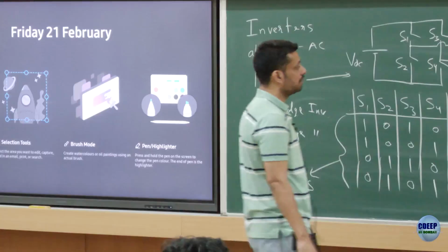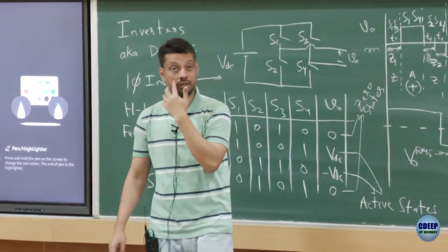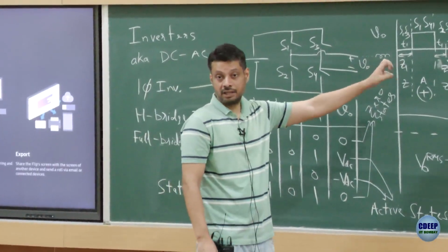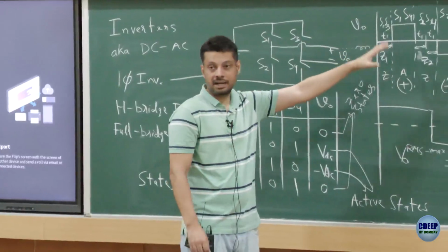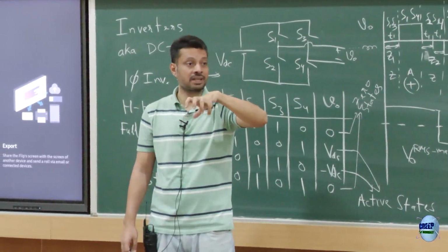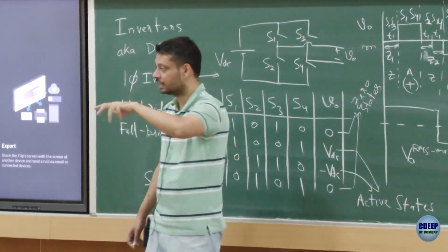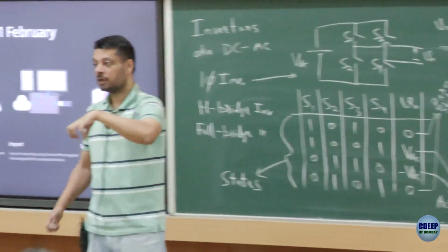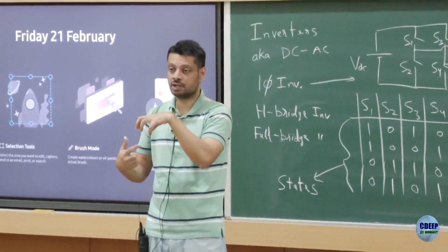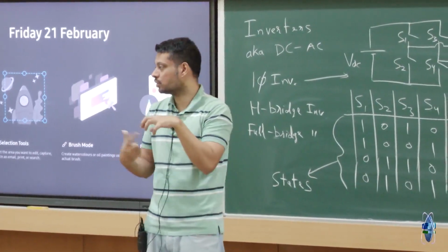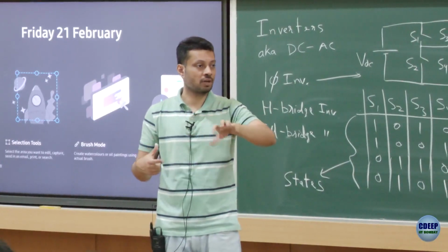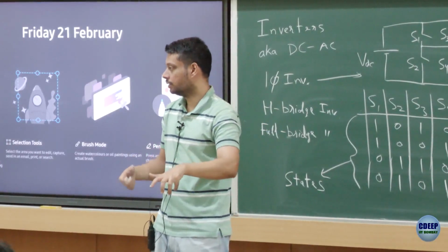Now if you see in a 3-phase induction motor, if you supply this voltage to it, it would draw some fundamental current and it would also draw harmonic current. And the motor will not work as smoothly as you want it to work, because it has a sinusoidal component, it's rotating, because the sinusoidal will lead to a rotating flux field which is also sinusoidal. But now there are these other harmonics also which would try to play around in that flux field and would create some sort of oscillatory or jerky motion of the motor.